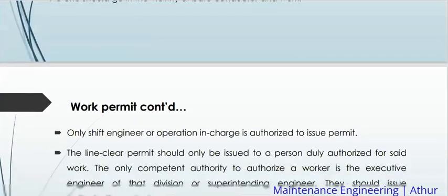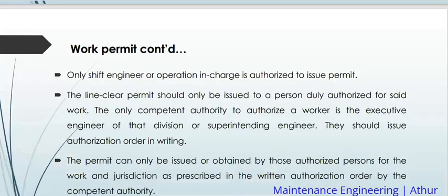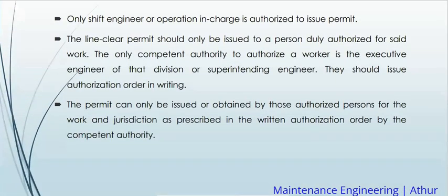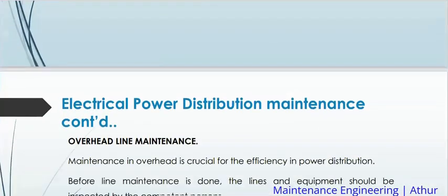That is the working permit. For you to do work, you must be authorized by an engineer who has to bring it and say, it's me who has put off the power, now the line is safe, you can start working. Still, even before working, you yourself are supposed to test the line and know, is there power?